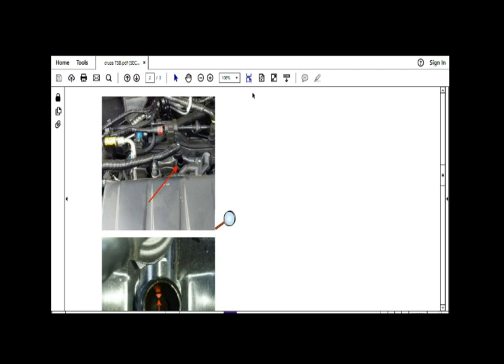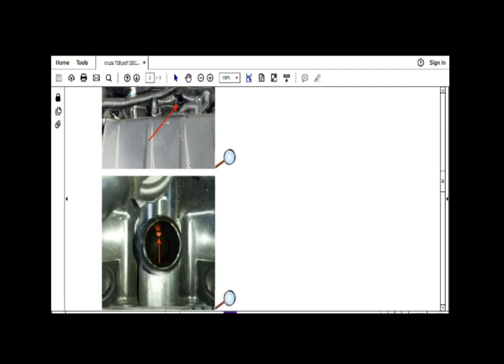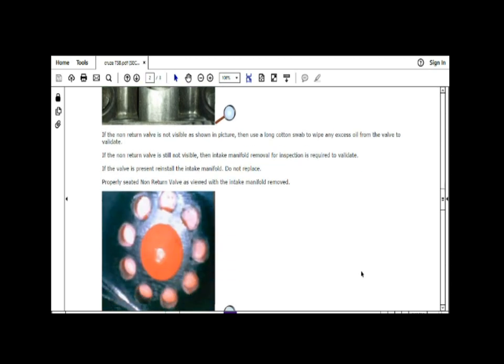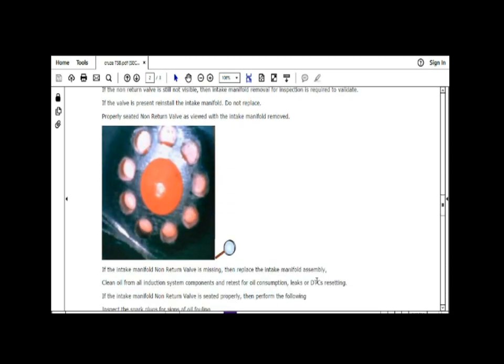It asks you to pull this hose off right back there on the intake manifold, and there's a little spring metal clip that you depress to pull up on the hose. It's got an O-ring that seals it. We scroll down, and we see that it identifies a small rubber valve that can be seen through that hole. It's telling you to look for this valve, as that's a valve that prevents boost pressure, during events where you would create boost, from entering the valve cover and creating pressure against the back of the PCV valve. That's what causes these PCV valves to rupture inside the intake manifold.